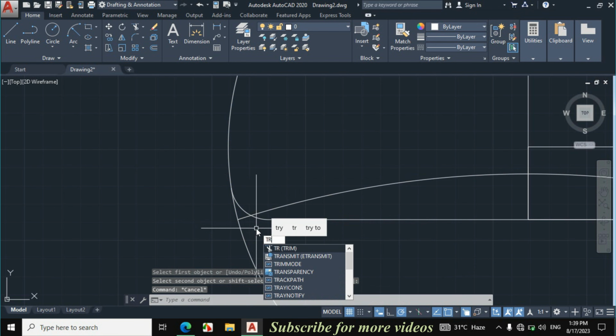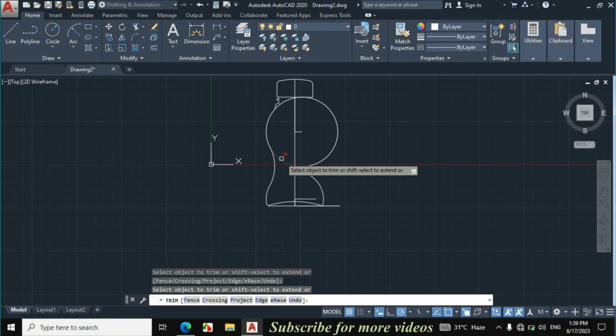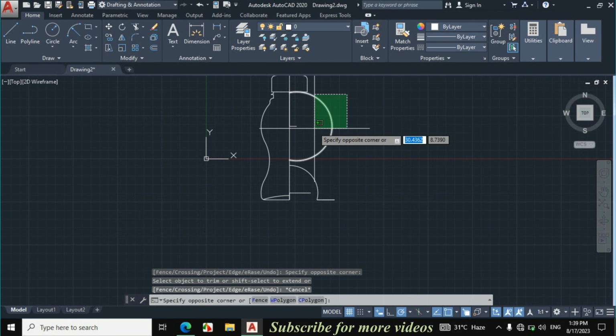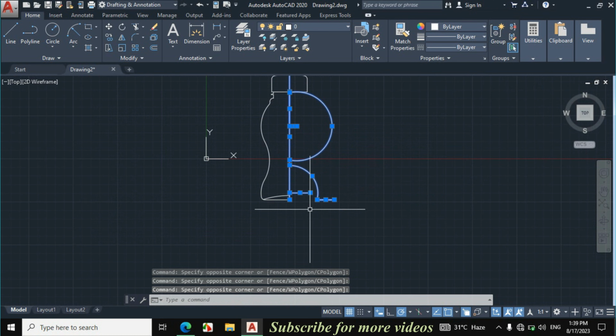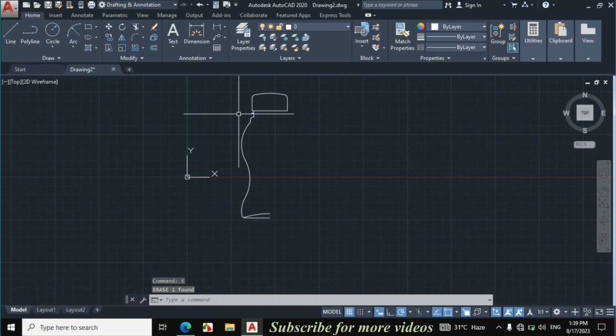Now trim this portion. So TR, double enter and trim this line, and this line, and this line, and all these lines. Now escape and select this portion, this line, and erase it. Also erase this line. Now I will mirror this portion.